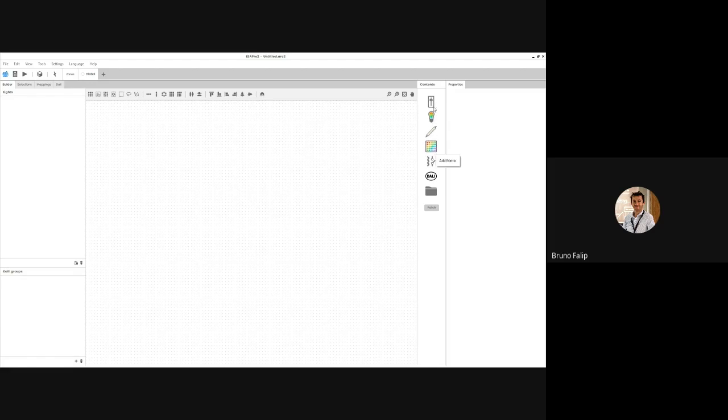Let's say you know already what you can do with DMX. So let's go directly with the DALI. There is this new DALI button here, which allows you to add your DALI devices to the software. One important thing also is, at the moment, it is not possible to do the commissioning with our software. We will supply a new tool soon, allowing you to create groups, address the devices and everything. But at the moment, with the software, we can only read that.